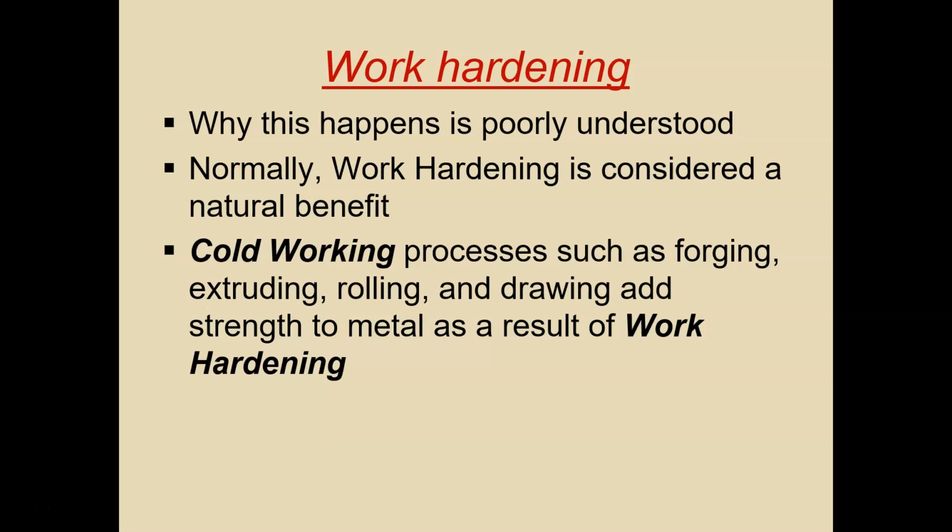Materials, while we're machining, work harden while we're machining. That is not a benefit. That is something we don't want to happen. A lot of different stainless steels, as you're machining them, the material will start work hardening, and all of a sudden, where you were cutting nicely, your tool bit starts burning up because the part is so hard. Or you go to drill it and the drill breaks off in it because it's work hardened. So you have to be very careful with your speeds and feeds and using coolants to make sure that your material isn't work hardening while you're working with it.